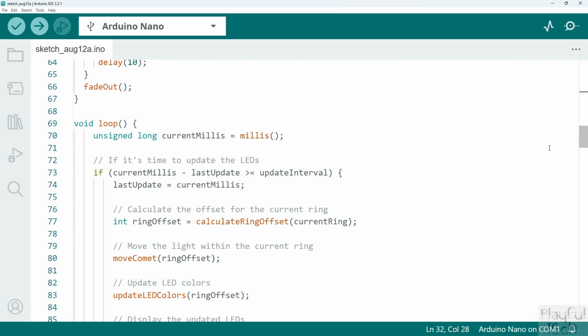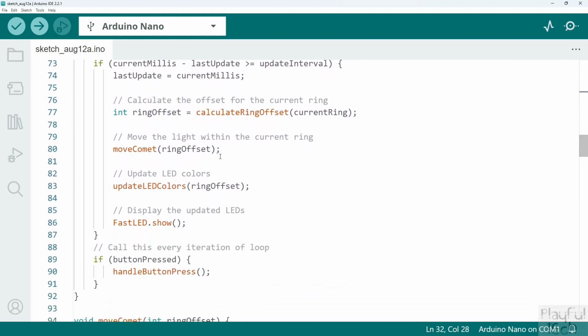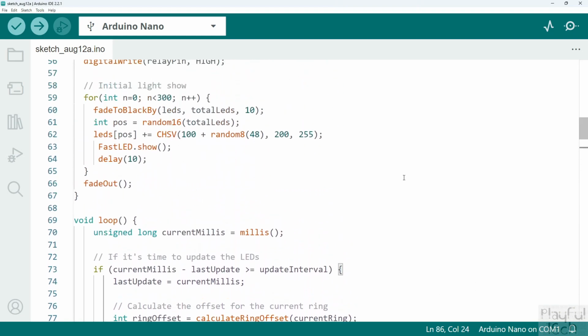In this project, I'm actually doing something a little bit different because we're doing all these animated effects and we're updating LEDs and making them fade out and things like that. These all take time for the processor to do, which means that the loop function gets delayed. It's got other work to do to keep the game running. And there's a risk that if you only checked for the input once each time at the beginning of loop using a simple digital read, you might not catch the button input.